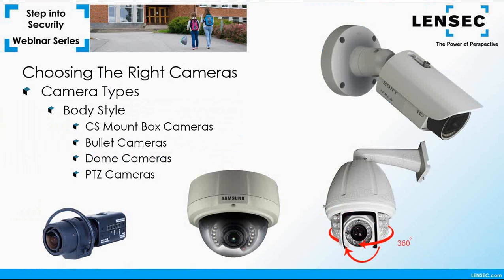Dome cameras in the center are very popular for both indoor and outdoor use. They sometimes have infrared illuminators built in and are usually ceiling mounted. If you have to wall mount them, you may want to consider a mounting arm that fits the base of the dome. They can be turned on their side, but that will affect the picture angle. A dome with a tri-axis capability gives you the ability to manually pan, tilt, and rotate the camera head to achieve the proper image orientation and field of view.